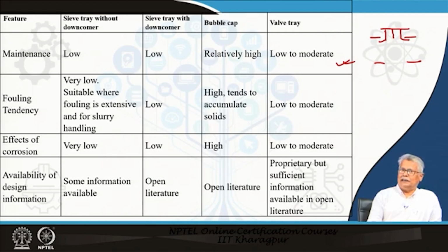In case of bubble cap, again there is a tendency to accumulate solid, because what happens is right on the deck, the flow rate of the liquid which is cross flowing through it is less, and there is a chance of accumulation of solids. In fact, if you really have to handle some liquid which has got a little bit of solids in it, you will prefer a bubble cap with a long riser and a good amount of skirt clearance, because this will allow a little bit of deposits to remain there.